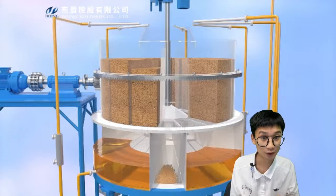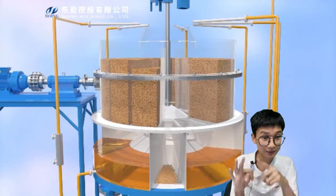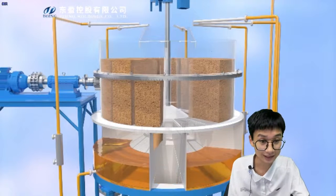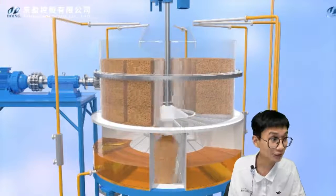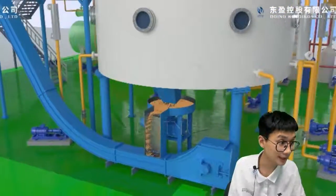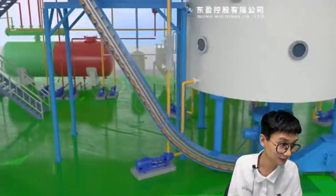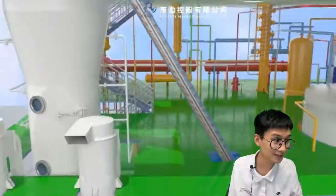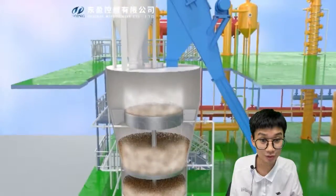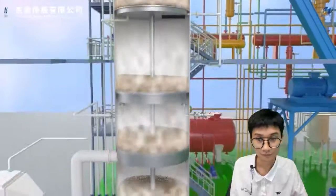After the 2 hours, the oil seeds with the hexane, we normally call the wet meal, and this is the crude oil with hexane, called micella. First of all, we will use the DTDC to deal with the wet meal, and for the micella, we will use the evaporative stripping system. The evaporative stripping system is for extracting edible oils. This is our DTDC machine to deal with the wet meal.